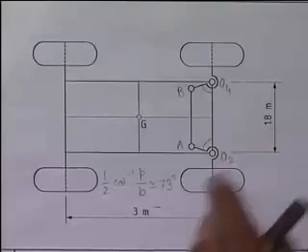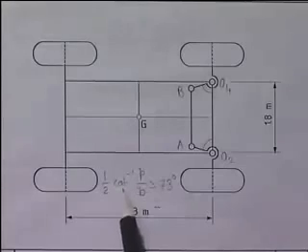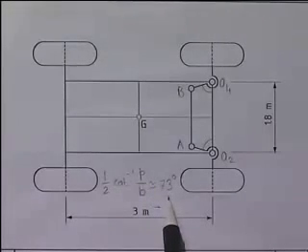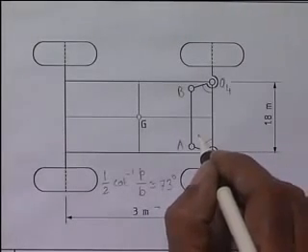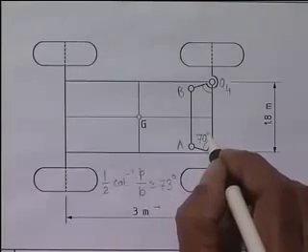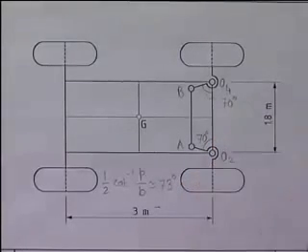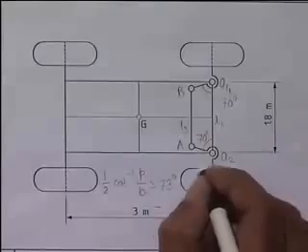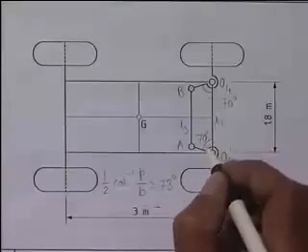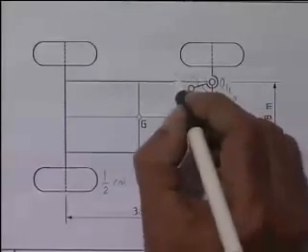For P equal to 1.8 meter, B equal to 3 meter, this angle, which we called alpha then, turned out to be half of cot inverse P by B, approximately 73 degrees. For this problem, we assume these two angles to be 70 degrees. Quite close to 73 degrees, I take this angle as 70 degrees. This angle is also 70 degrees. This is L1, this is L3, and O2A and AB are same, which is say L2. This length is L2, this length is also L2.